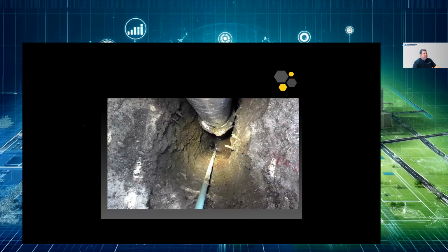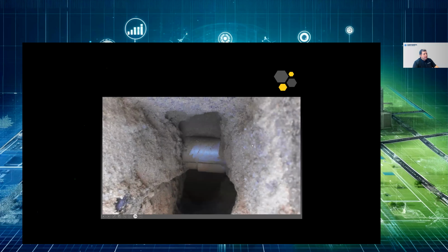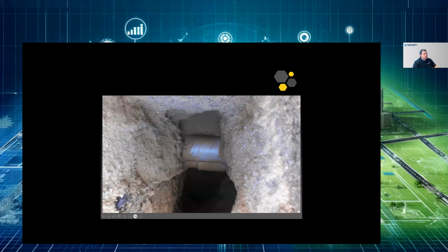After we dig, of course, you shed some light. You look there and you confirm that you find the utility you are looking for. And here is the pipe. Usually, before we backfill, you have a survey crew that goes ahead and shoots the top of the pipe. Of course, when this utility goes into the mapping phase, it is assigned as utility level A.